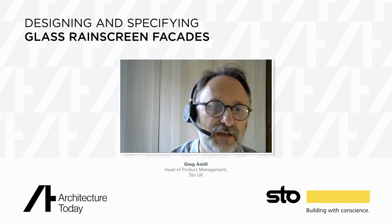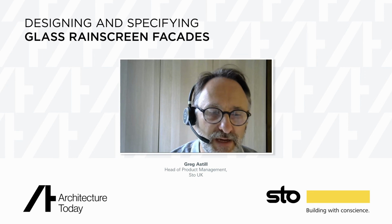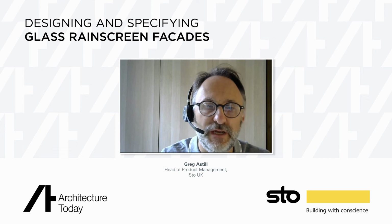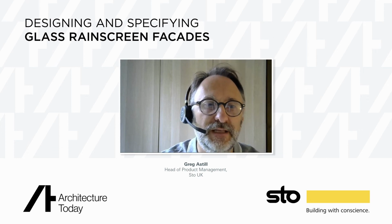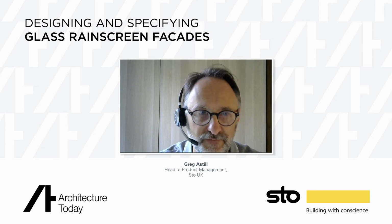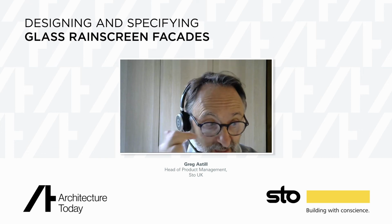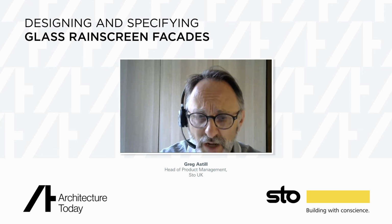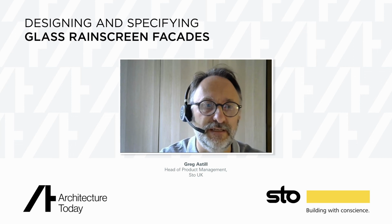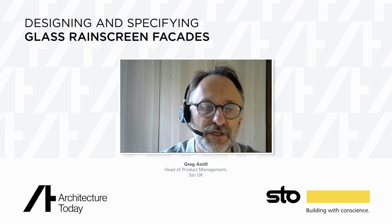You basically get a rating from the blast test. So you're looking at, again, typically the amount of spall. It's known as spall, the amount of material that comes away from the glass panel and then scatters by virtue of the sort of suction of the blast. So a blast wave goes out, creates a pressure wave which hits the panel, but then you get air rushing in to fill that vacuum that's created, and then you get a lot of suction on the panel system itself, and that's when damage can occur.